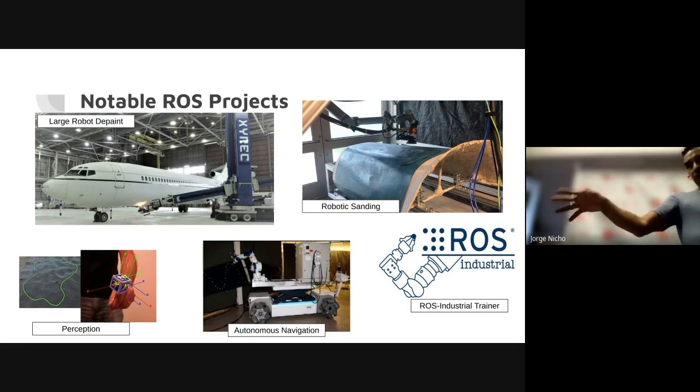At the bottom on the left-hand side, there's that perception application. So we had this vision algorithm that we wrote also in ROS to track that box there where you see the AR codes. So basically we were using that system to then teach a robot how to do a task. We would use the wand to move it around in space, capture the waypoints using the camera system, and then we would tell the robot to go and follow the path in order to carry out a given task, right?